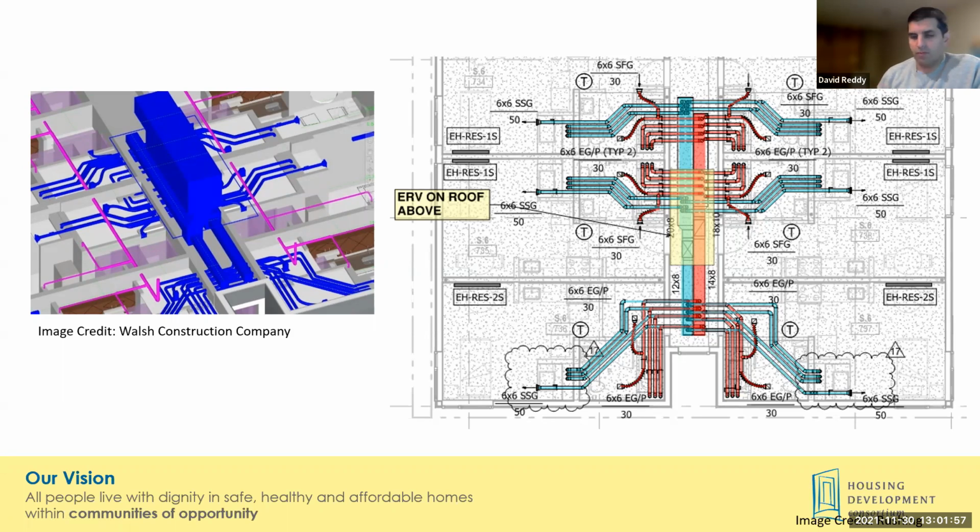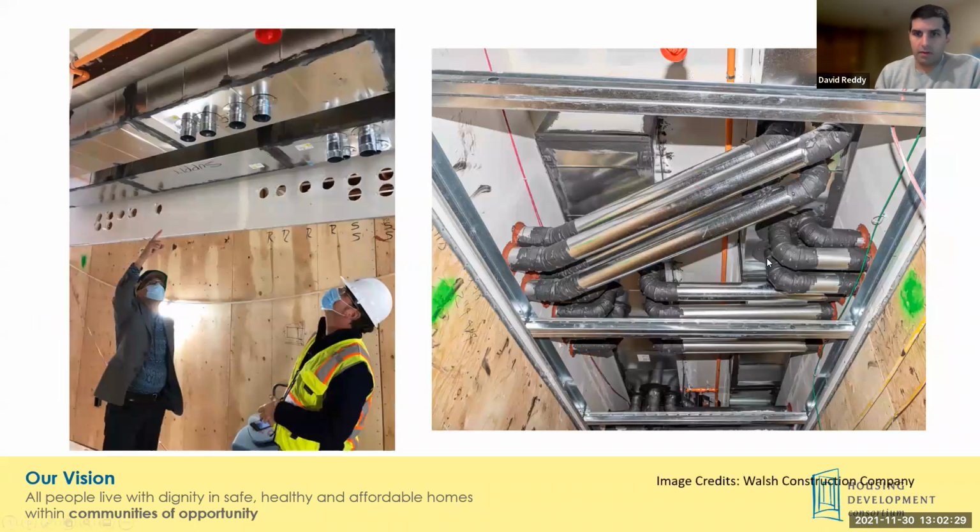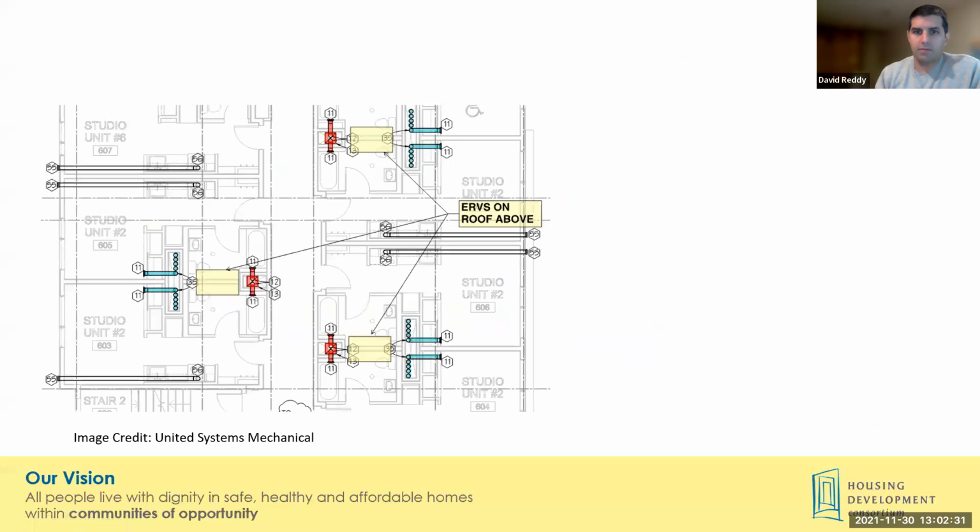And it was done in part for passive house, but also recognizing that tenants for their buildings weren't necessarily cooking a lot. And so the benefit of a fully ducted exhaust range hood, it was felt that the balance between providing continuous local kitchen exhaust with the ERV and the recirculating hood was the better solution for this passive house project. So that's one fundamental difference that you can see between these two approaches. This does show the vented exhaust range hood here separately.